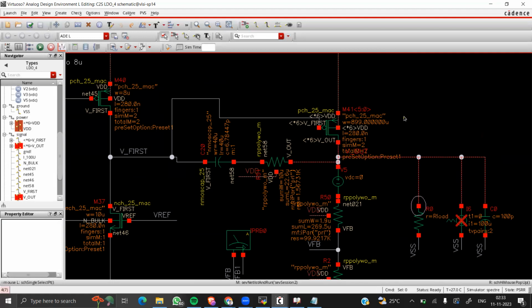Hence, we see that an LDO basically needs at least a voltage drop of a threshold if we are using an NMOS. Generally speaking, some industrial applications ask for a low dropout regulator in the range of around 200 to 300 millivolts. If we have those constraints, then it becomes very difficult for us to use NMOS devices, at least for a longer channel. The corresponding design is in 65 nanometers, and the threshold voltage is around 450 to 500 millivolts. So in that case, we would not be able to use an NMOS.